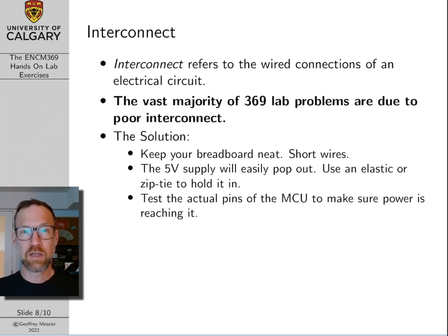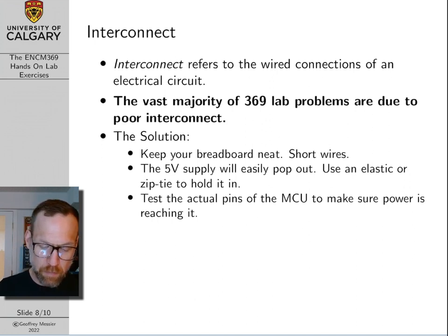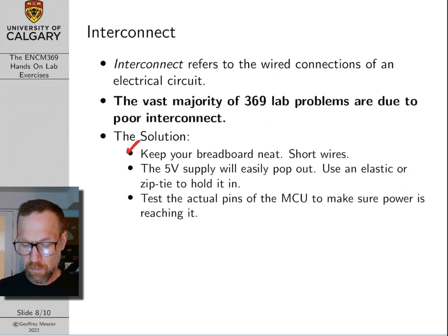When I worked in industry, I had a whole job for a while just taking care of all the special cables that were used to connect various equipment modules together, and making sure you've got the right cables that don't wear out. It's a huge thing. So here's a couple of tips that you absolutely have to follow when you're doing these labs. First of all, keep your breadboard neat. In particular, use very short wires.